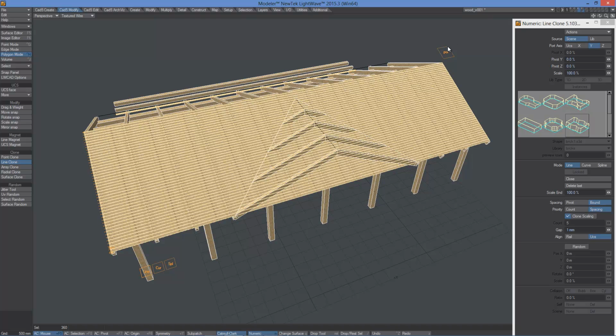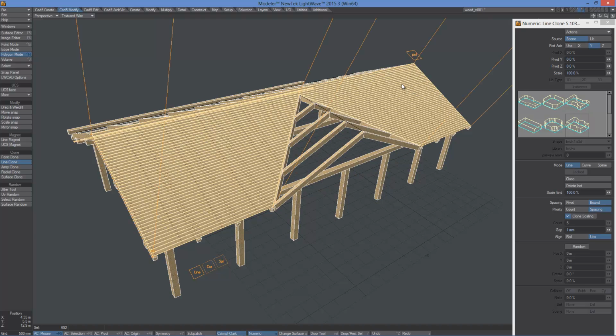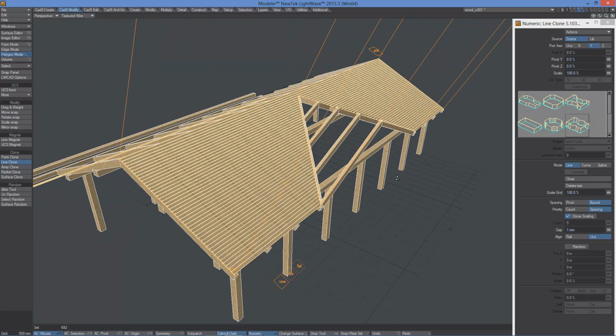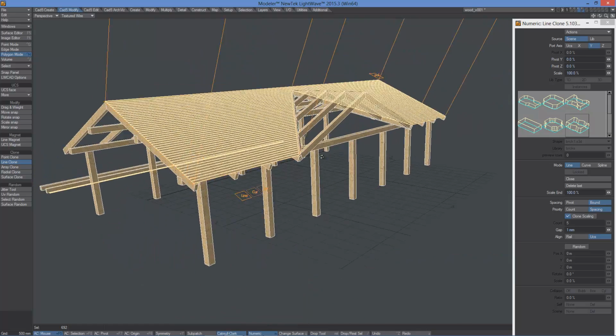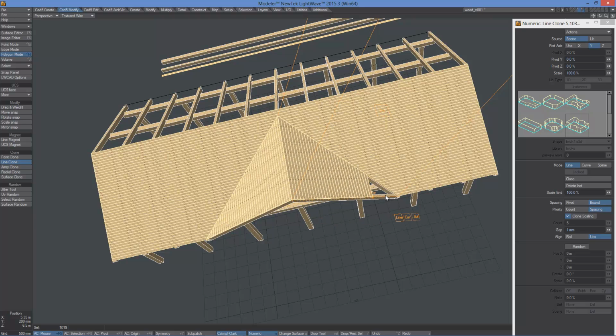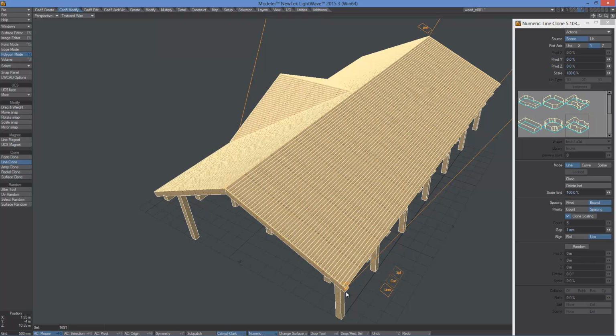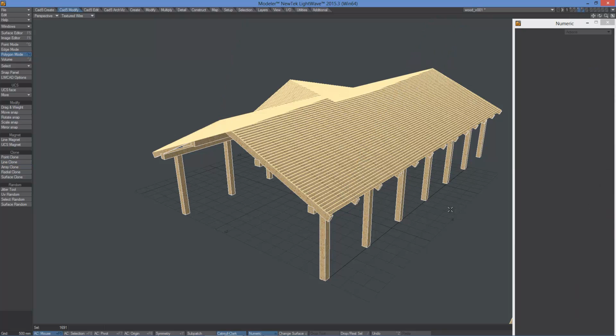And we can also use this polygon OpenGeo button, which makes booleans between clones and the volume area created from the selected polygon. In our case, it is the roof polygon which we created before. So with polygon area booleans, we can immediately create a final cloning of the plank on the roof surface. Same way we can create other clones, so this way we can put planks on any kind of surface really quickly and precisely. And done.